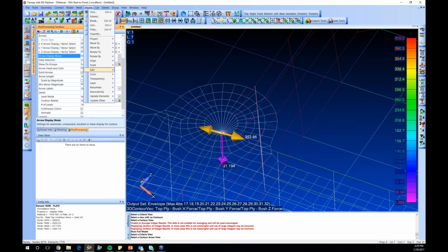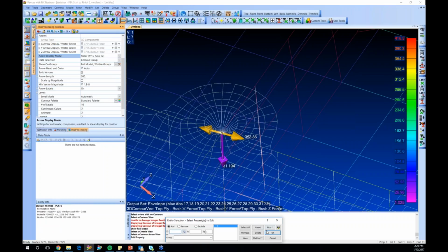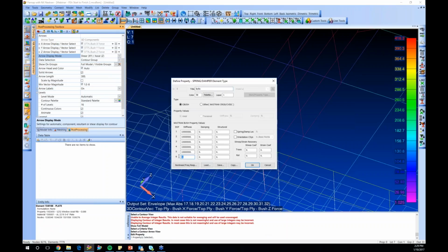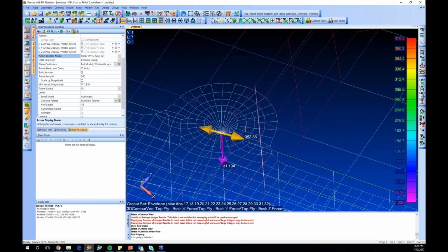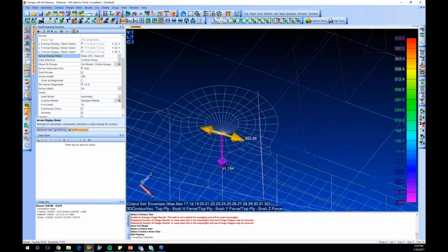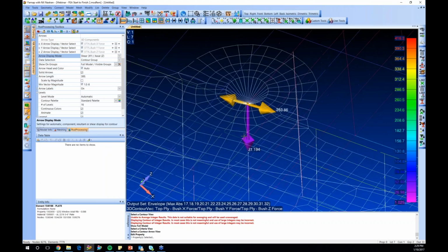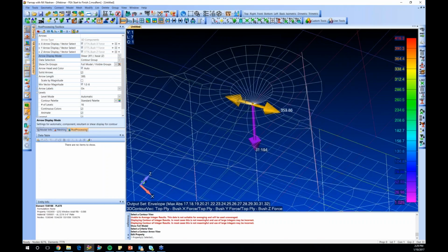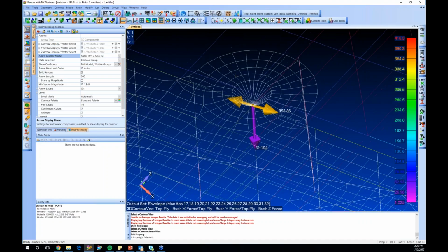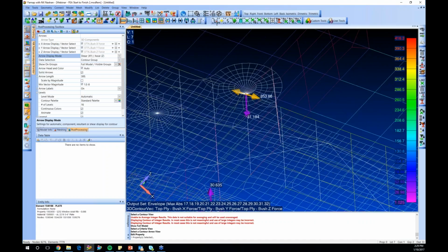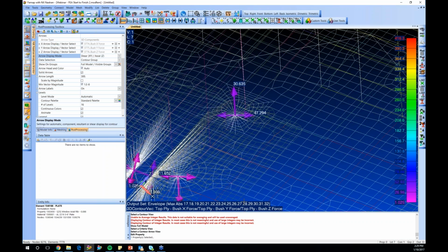Yeah, modify edit property. And if we click that C-bush, you'll see we've got our free dimension in the 6, which is Z. So we've set that as axial, so that's right. And it automatically resolves your shear and tension for you. So we know that on this bolt, there's 350 pounds of shear and 31 pounds of tension. So that makes it easy to see where these bolts are and how much loading is on them.